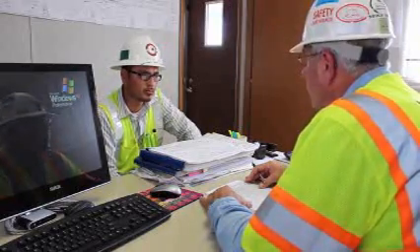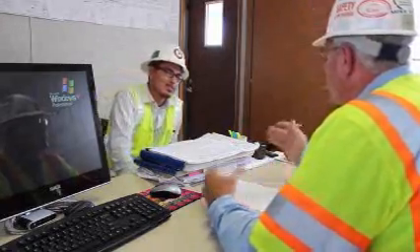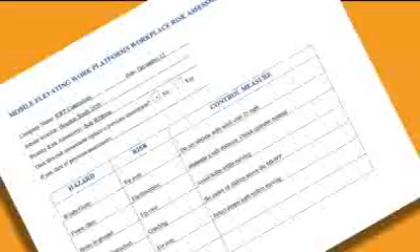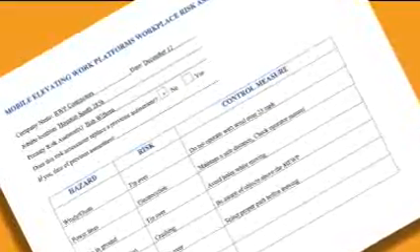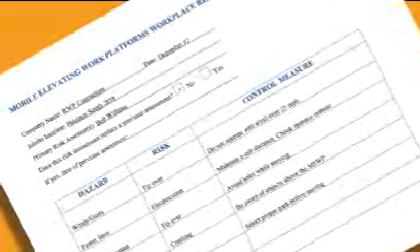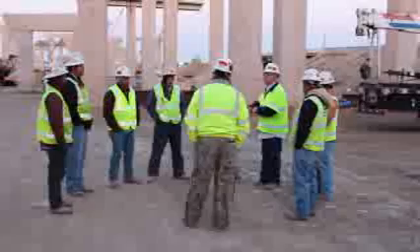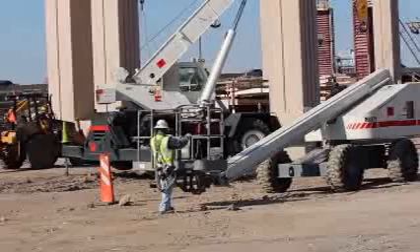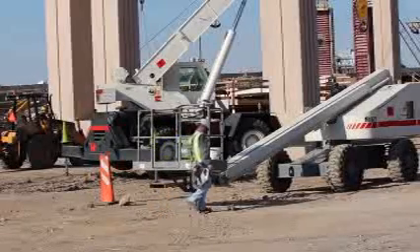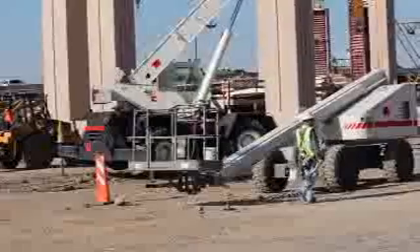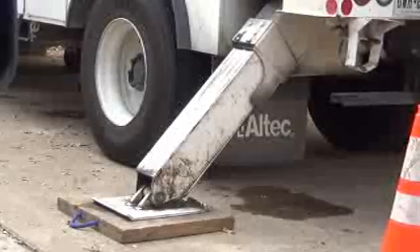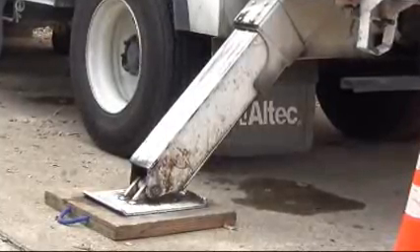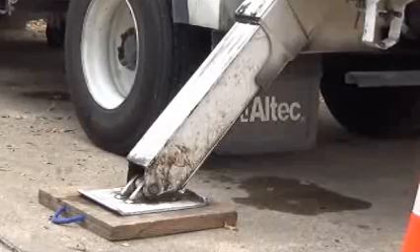A safe use plan must be developed for each MEWP and must include, at a minimum, all the following items. A worksite risk assessment is necessary to identify hazards, evaluate any risk, create control measures, and communicate results with all affected employees. The plan must include the selection, provision, and use of appropriate MEWP and associated equipment. Additionally, the plan needs to provide for an assessment of the support surface and its ability to support the MEWP.